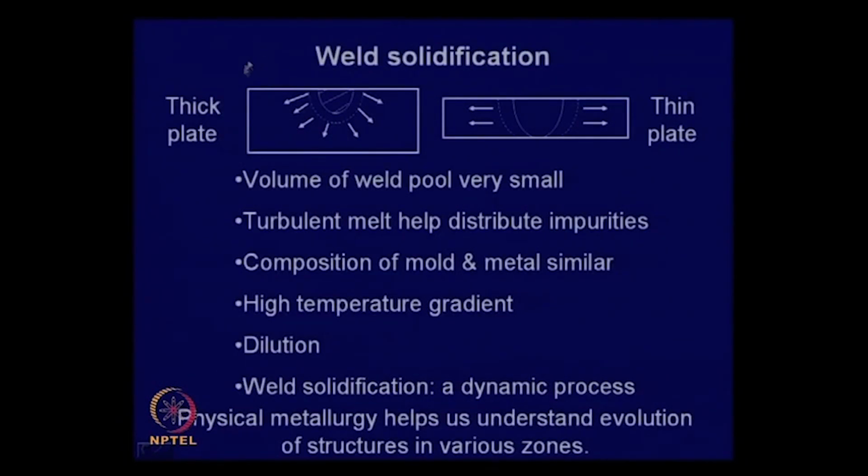Schematically, the heat transfer is shown here for two cases. First, thick plate. Imagine this is the molten pool, and surrounding it a thin layer gets melted and mixed up with the weld pool. Here the heat can flow in all directions, including through the thickness direction.